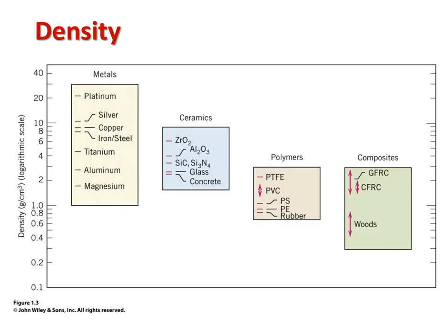Now, in terms of the losers, we can say from a lightweighting standpoint is metals. Metals definitely top out the density scale, with the highest for platinum group being above 20 grams per cubic centimeter, and the lowest for magnesium and aluminum coming in, more or less even with the more dense polymers.